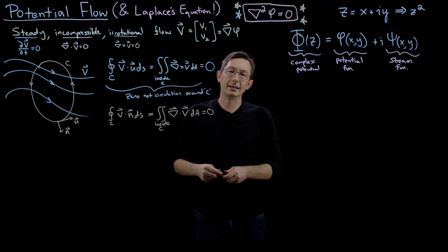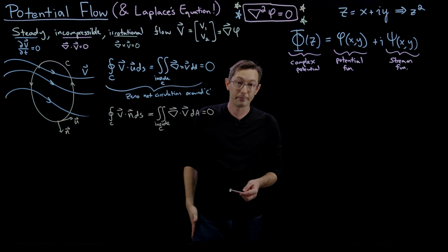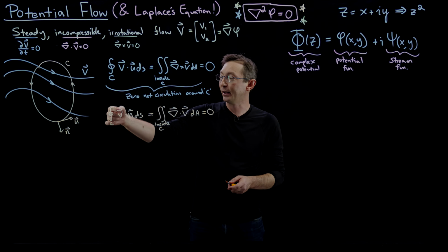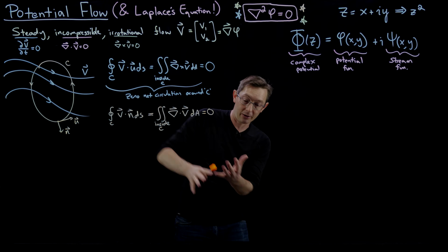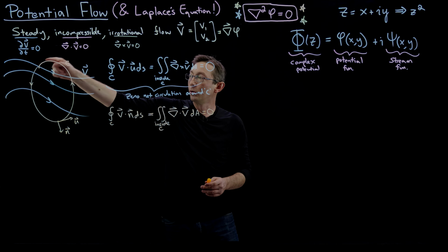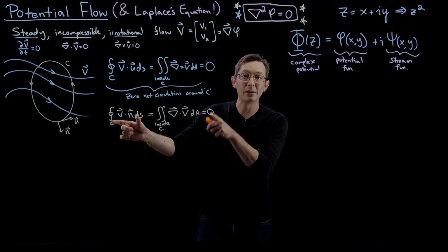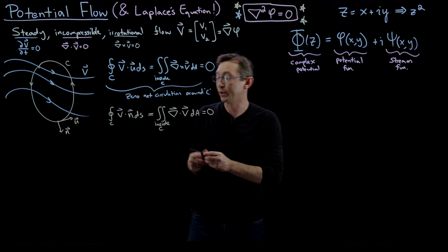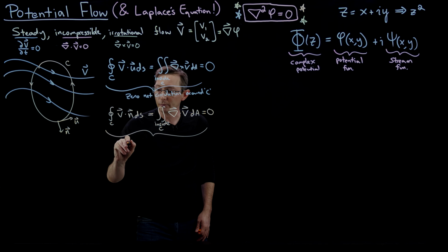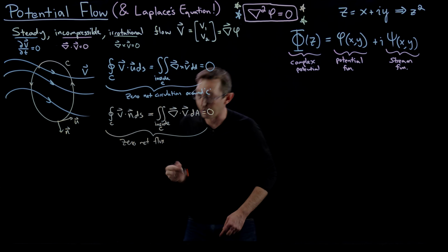And so we know that there is no net component of V integrated on the surface. And this was that flux integral that we had been looking at before, where we integrated the component of V that's carrying you out through the normal direction of the surface, integrated on the whole surface of the flow field. So this essentially is a statement that there is zero net flux through the contour. So this is zero net flux across C.